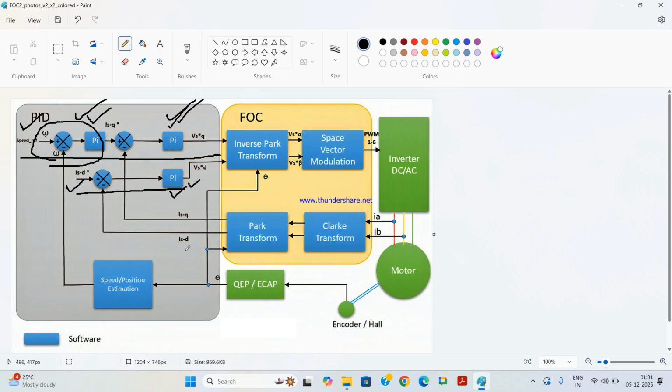Another is, you consider the excitation. This is without excitation, the solution whatever you are getting, that is called the complementary function, and then you have to calculate the particular integral, and both club together, and it will give the instantaneous output. So this complementary function is the transient response of the system, and this particular integral, that is the steady state response.